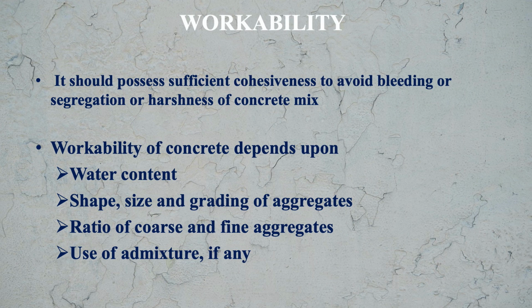Workability of concrete depends mainly upon water content, shape, size and grading of aggregate, ratio of coarse and fine aggregate, and use of admixtures, if any. If you are using admixtures, certainly that will govern the workability of the concrete.